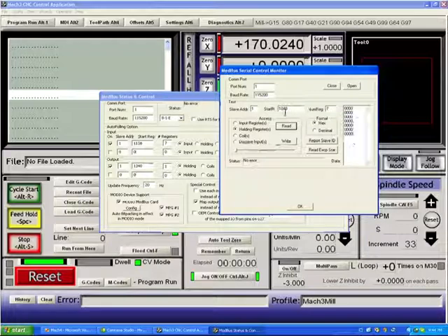and you can see that we can still read from 1040, although it doesn't make any sense to do so because they are registers meant to write data to, and they're all set to 0 at the moment. If we hit write, we have no error listed, and we did write data to the board. You could set a bit pattern into these hex bytes and hit write, and on Peter's board inputs will become active immediately when you hit write because the terminal strip will then reflect what was in these boxes. So this is a good way to test a ModBus device.